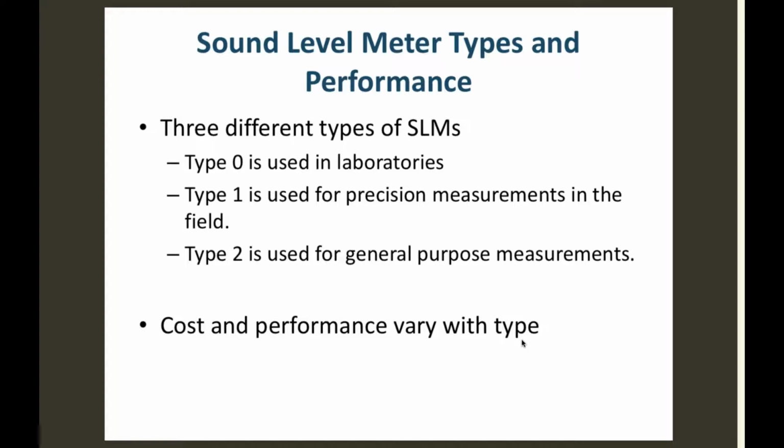Okay, here's a sound level meter. This particular sound level meter can be programmed for A scale, C scale, and Z scale. It's currently programmed for A scale. You'll see it on here. It'll say LAS. L is for sound pressure level, and AS. And right now, as I'm talking, it's reading about 70 decibels, 75 decibels.